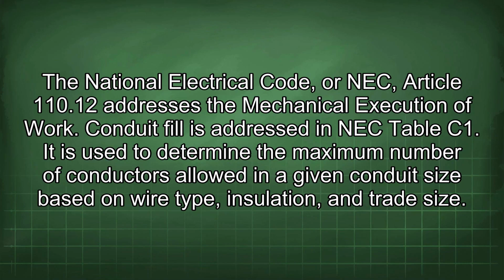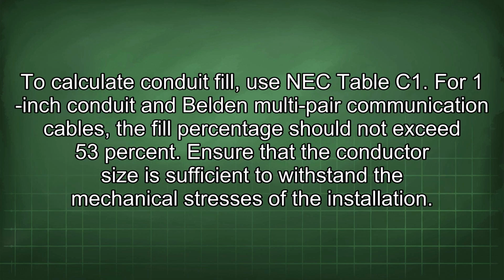The National Electrical Code, or NEC, Article 110.12 addresses the mechanical execution of work. Conduit fill is addressed in NEC Table C1. It is used to determine the maximum number of conductors allowed in a given conduit size based on wire type, insulation, and trade size. To calculate conduit fill, use NEC Table C1.